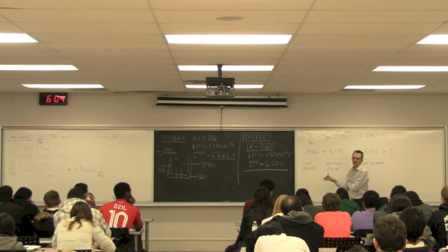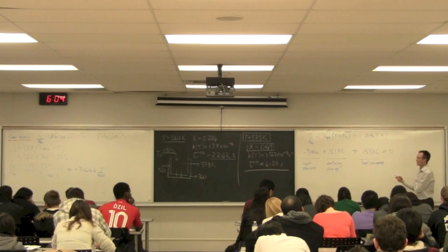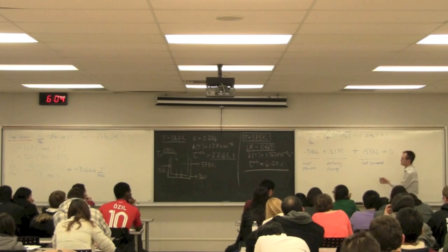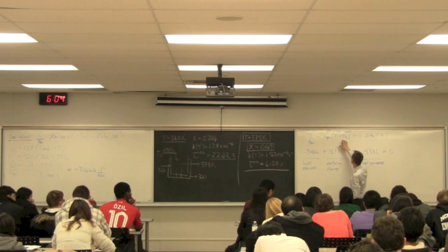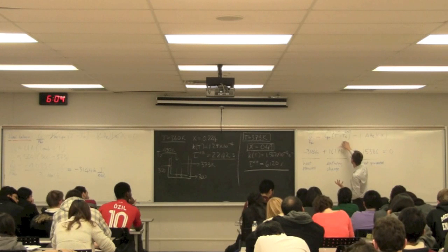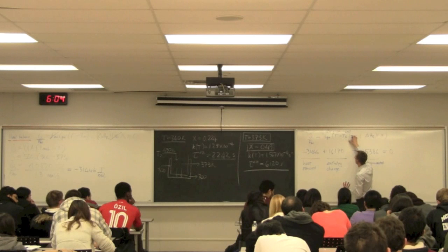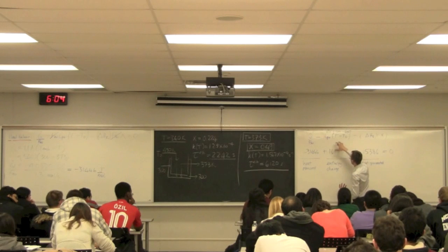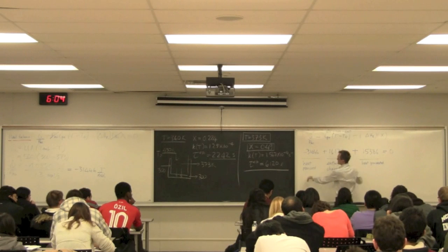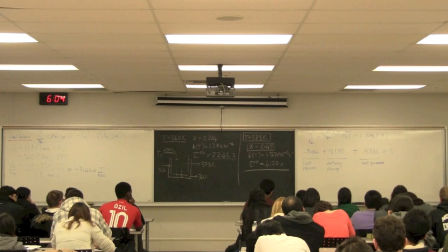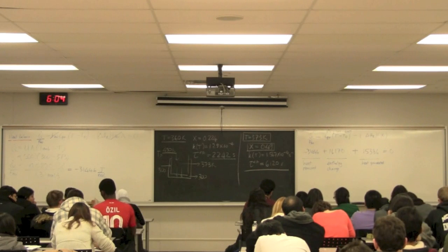If I'm looking at optimizing this process's energy profile, it would be very straightforward to bring in, if possible, cooler material. We don't know what's coming upstream and we don't know the reason for this entry temperature being 450. But if we could cool that down in some way, I've got less enthalpy coming in, and then I have to remove less heat out of the system. I can reduce the load on my utilities in this particular process.